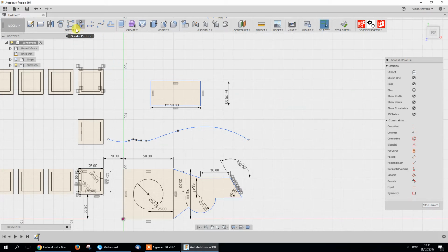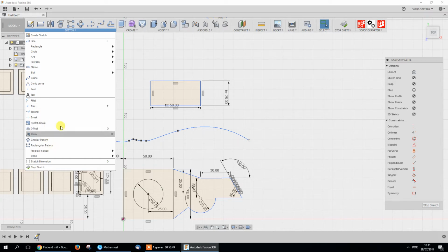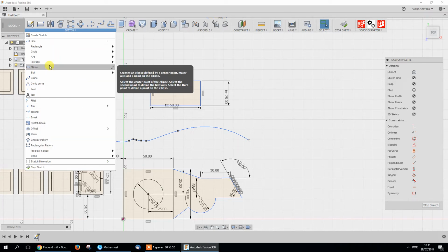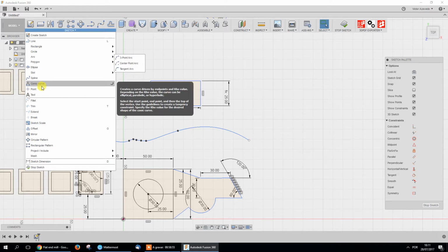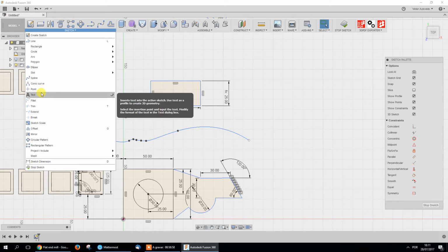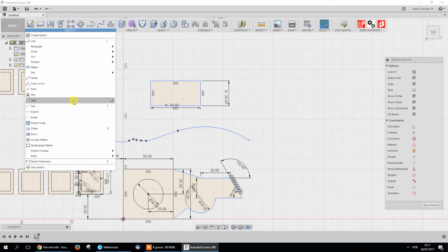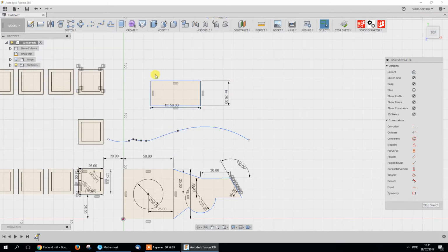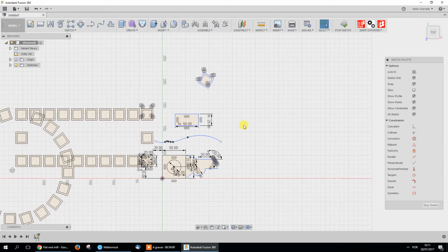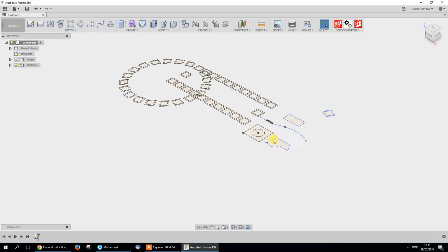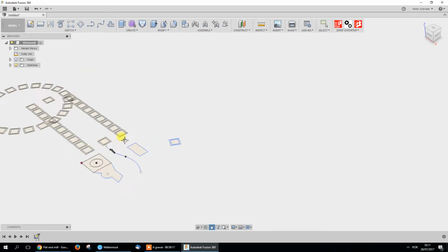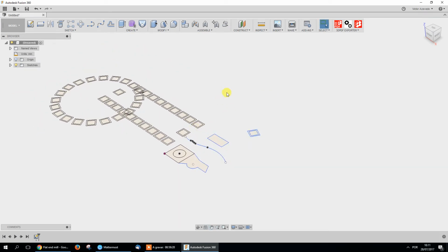And this is most of the options you're going to use. This, rectangle, line. There's also ellipse, polygon, arcs, conic curves, points, text. All different things that you'll find out later during your work. So now that you've designed what you wanted, you can stop the sketch and it will give you a small preview of your design. Now we want to actually create a 3D feature.